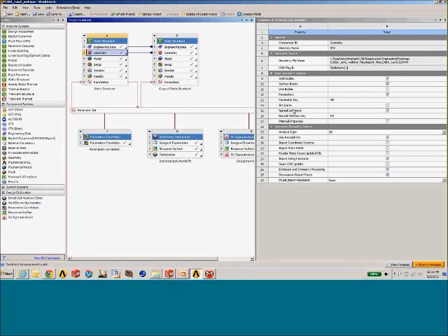We do the same thing with name selections. Click on the name selection box and specify the parameter prefix that we're using for the name selections. Keep in mind that if I leave either of these 2 rows blank, I'm going to get all of the parameters or all of the name selections that are defined in the model. Now, that can be a little cumbersome when it comes to the parameters because CAD models typically have hundreds of parameters associated with them. So you'll have this long list that you'll have to filter through to find the ones that you want to operate on. I advocate keeping your life simple, specifying the prefix for the parameters that you want, and then just simply extracting those parameters when you bring that geometry into Ansys.